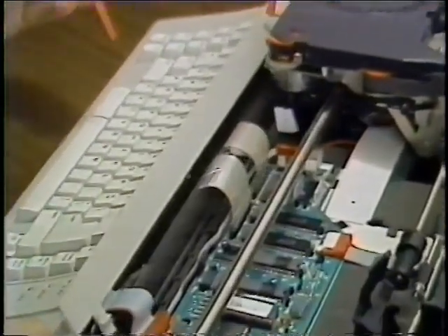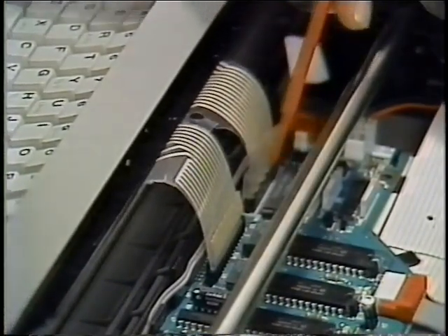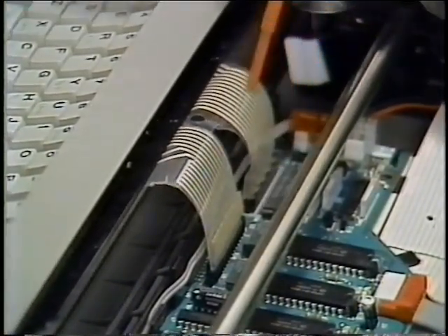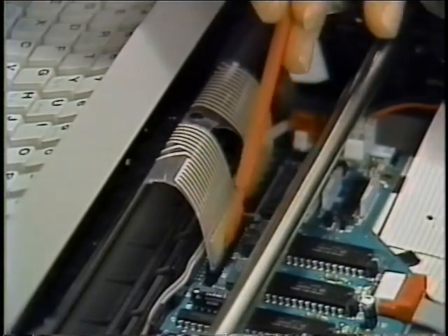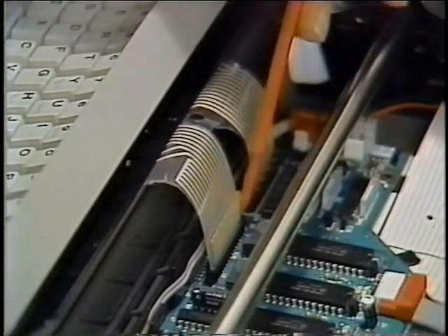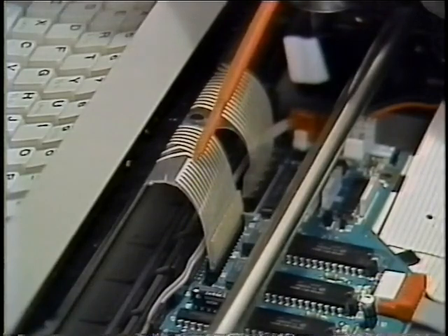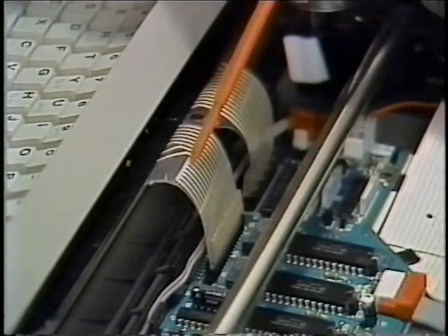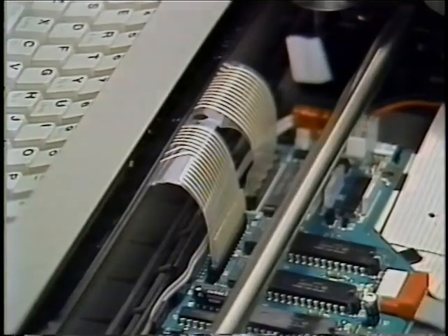This is connector J1F. This connector is where the 13 keyboard drive lines plug into the function board. This is connector J2F. This is where the 8 sense lines plug into the function board. Notice that you have 7 additional lines on the right. These are the keyboard ID lines. They will be discussed later.